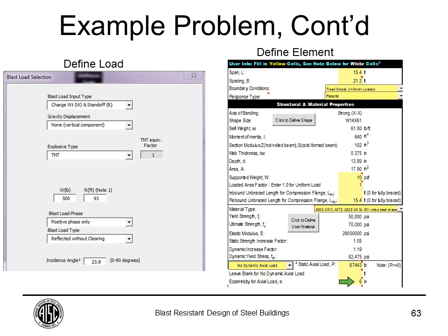SBEDS allows you to account for an eccentricity depending on how your connection is detailed, and that includes the P-delta effects. The way the P-delta effects are included in SBEDS is a little bit different than using the magnifying factor approach from the AISC code, because that presents some complications when you get into the plastic range. So what SBEDS does is it calculates an equivalent lateral load, a uniformly distributed load, that gets applied at every time step and causes the same effects as the P-delta every time it gets deformed. So depending on the detailing of your connection, you can include that, and SBEDS will take into account the P-delta effects for that case.